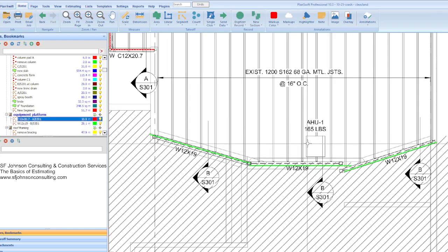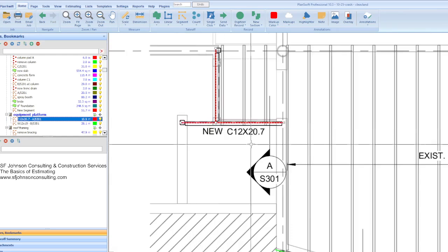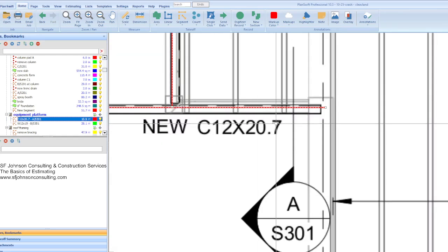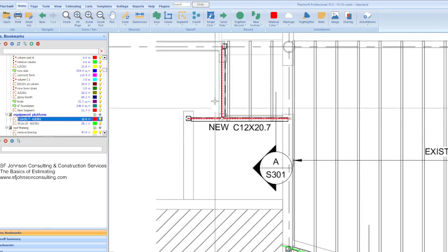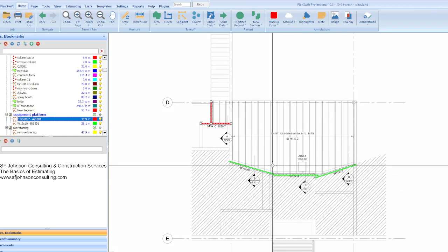And then we also had some C beams, right? So we have different ones. This one says that this C beam will weigh 12.7 pounds per linear foot. And so we do the same thing: however many linear feet times 12.7 gives us how many pounds, and then we're able to put that on our estimate.